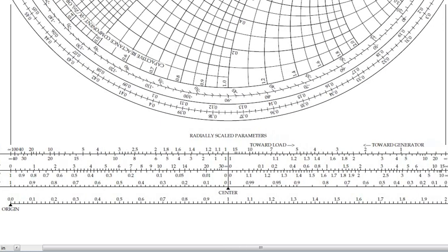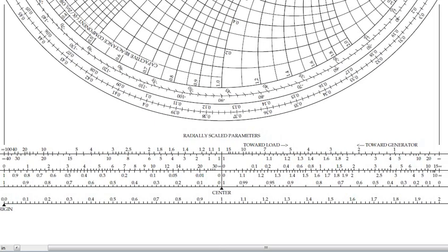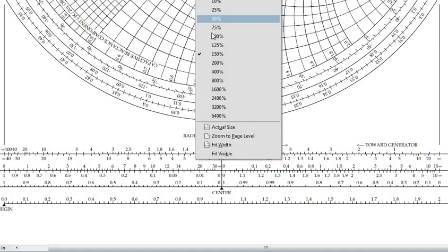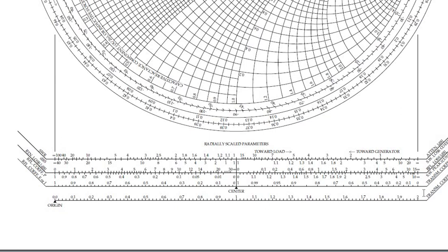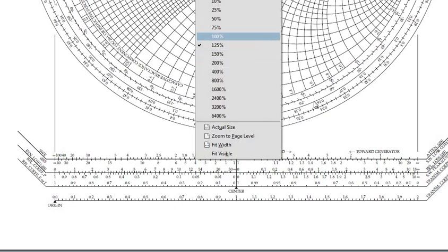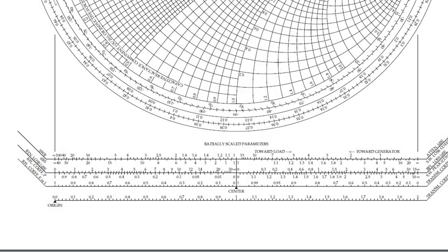On this left hand side we saw, when you move to the right hand side, by decreasing the size, here also the transmission coefficient exists, the transmission coefficient and SWR, and here also some parameters exist. For those parameters we are going to use all these scales. Here we are going to use the SWR scale and the reflection coefficient scale. Then we will move in the upward direction.